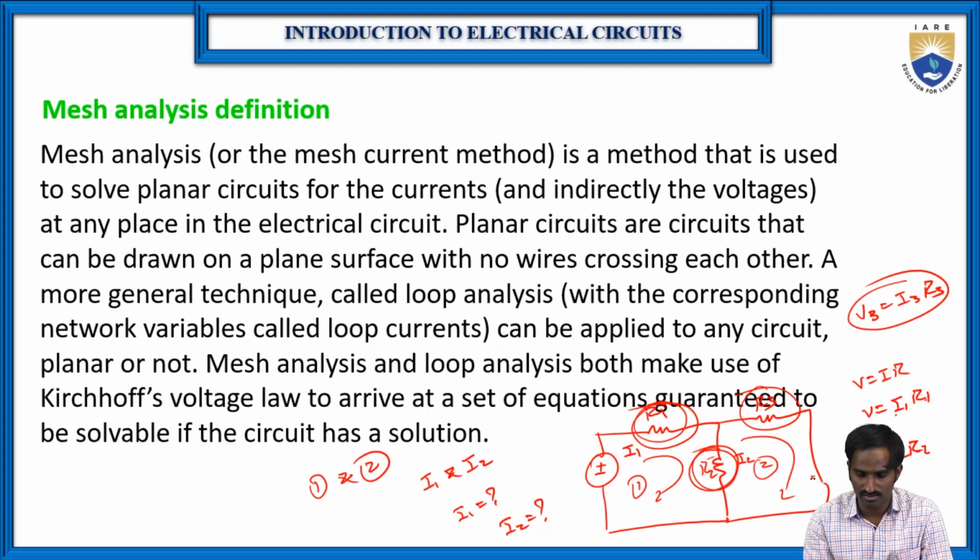Of course, this is the same thing that they have written. Mesh analysis is a method that is used to solve planar circuits for the currents. Indirectly it gives the voltages, because if you find the currents, then from the currents we can find V1, V2 and V3. Planar circuits are the circuits that can be drawn on a plane surface with no wire crossing each other. Of course, we know already what is meant by a planar circuit. The branches should not overlap with each other. Those are called planar circuits.